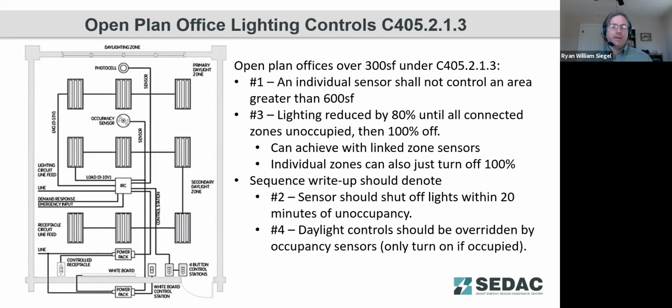Also noting here that 20 minutes of unoccupancy is the trigger point, or no greater than 20 minutes. Some spaces, particularly now with LED technology, because they don't mind switching nearly as much as the old fluorescents do, it's not uncommon where we see certain locations that may be less than 20 minutes, where you have a 10-minute or even just a 5-minute delay.